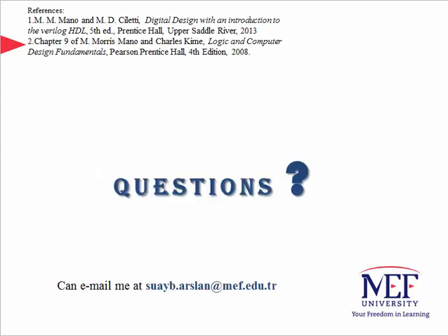So in this class, we covered an overall design of a simple computer that consists of two main components called datapath and control unit. We have seen that coming up with the best computer architecture is heavily dependent on the choice of the instruction set. The experience with the best set of instructions is usually attained through long years of experience, yet we have shown well-known and used basic design methodologies that lead us to an understandable and neat design of a single-cycle hardwired control and controlled computer.